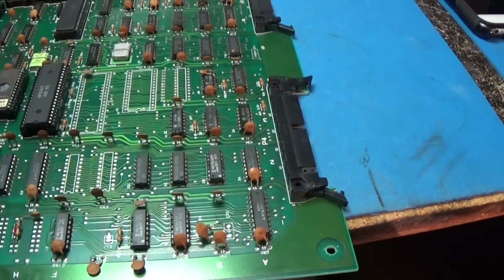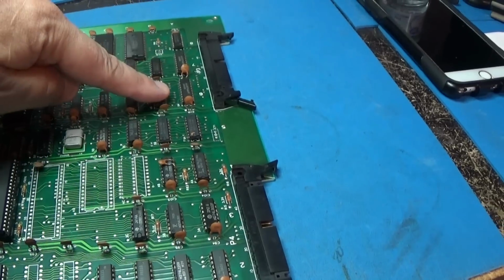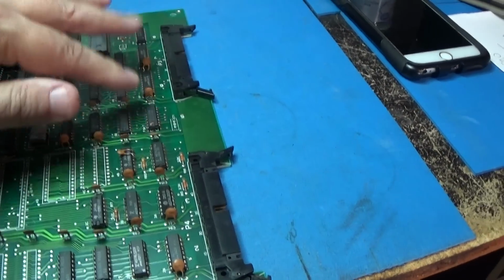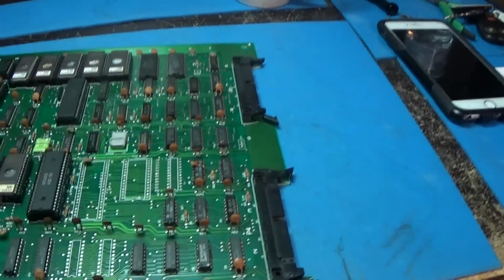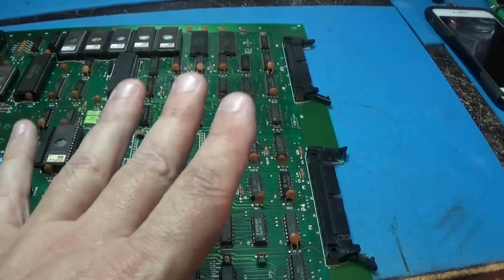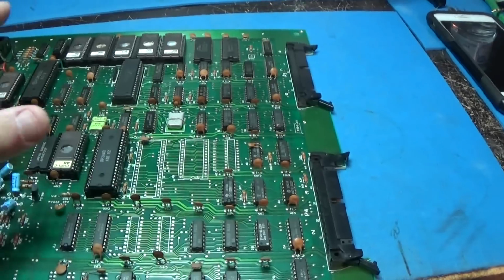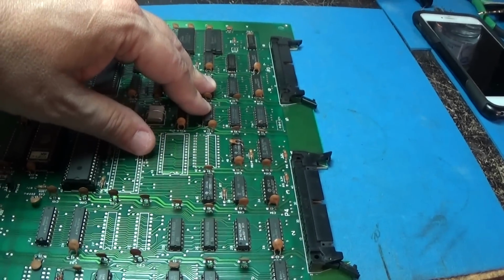Okay, now that work is done. It's this chip, this one, and this one. Those 4 161 counters make up the DMA addressing. So those are new, so that is not going to be a problem anymore. If I see that flakage, then it's actually going to be something either in the timing, the clocking, or something on the other board, the video board.